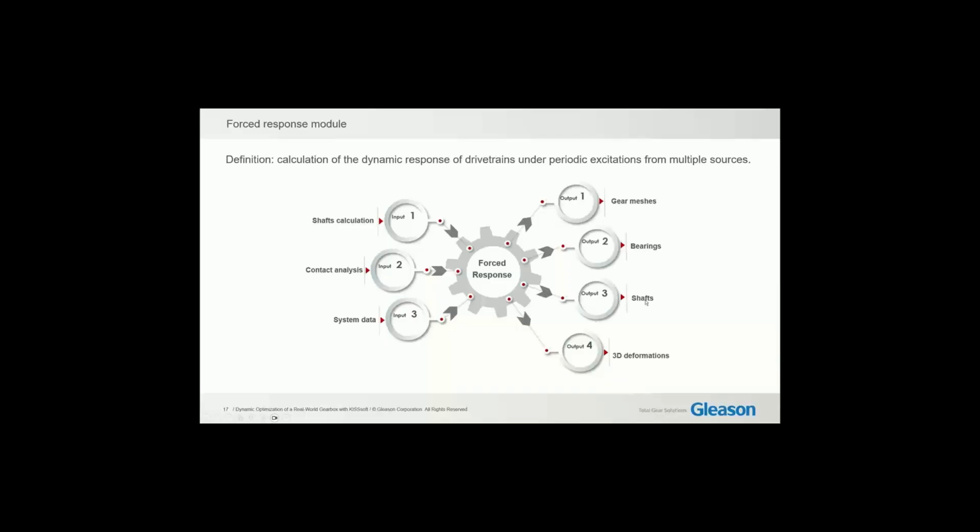For outputs regarding shaft, we can consider some documentation points and calculate displacement, velocity, acceleration, or other values, for example forces and moments at a certain section of shaft. And finally, we can visualize the system in 3D to better see the effect of excitation on different components.